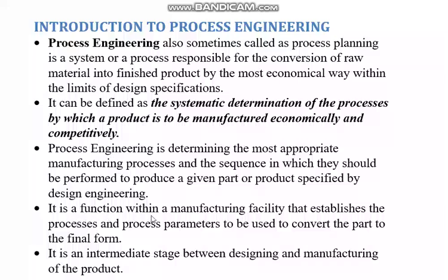Process engineering is a function within a manufacturing facility that establishes the processes and process parameters to be used. Now here they are talking about some more things. Process parameters means, if you're working on a lathe machine, at what speed and what depth of cut you will be using. Those are the process parameters for a lathe machine. Similarly, for other processes, other parameters will be there. You have to determine those things also.